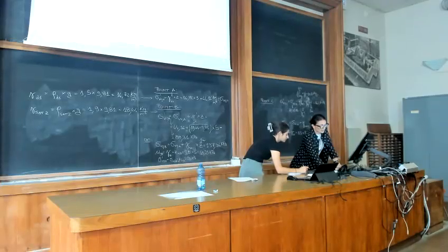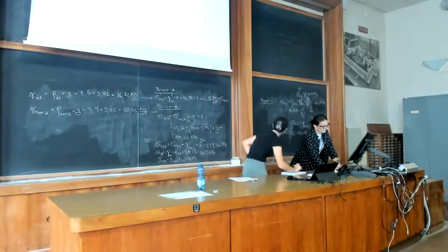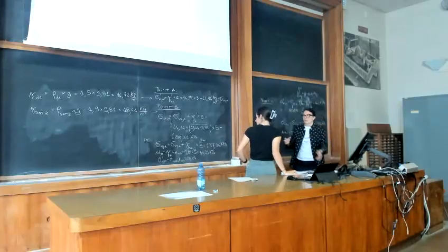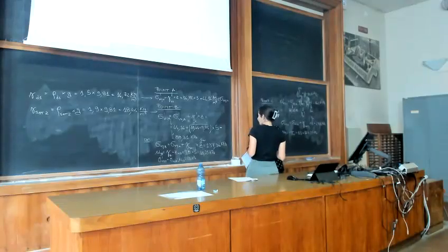So effective stresses are gamma dash multiplying the depth. Total stresses, which are sigma, without the apex, are gamma sat multiplying the depth. And remember that the response of soil is regulated by the effective component of stress. So it is very important that we consider it.